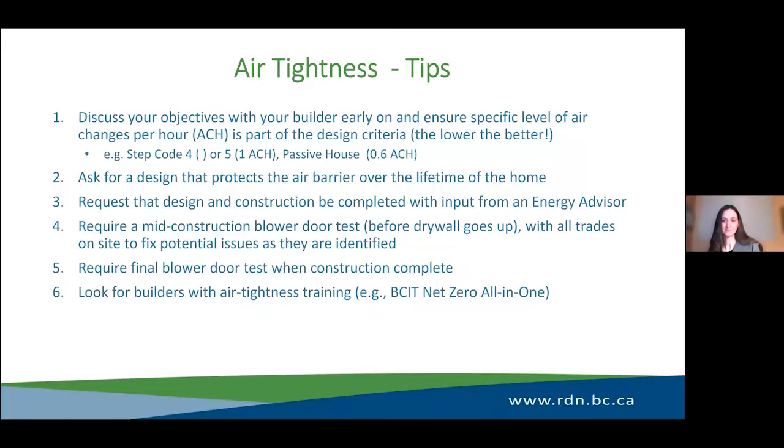It's very difficult to fix air barrier issues once all of the drywall goes up and the house is finished. And then doing a final blower door test. And then looking for builders who put extra effort into air tightness, either through training or through building of high performance homes in the past.